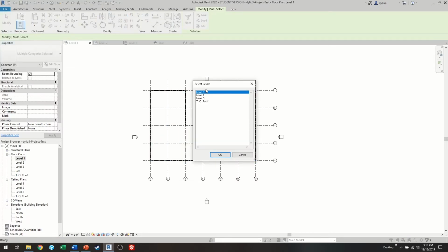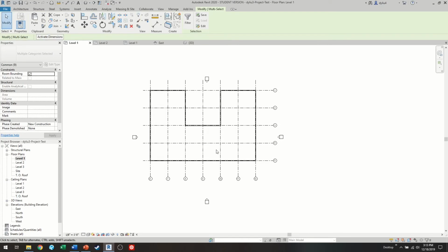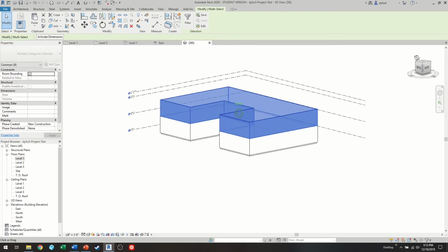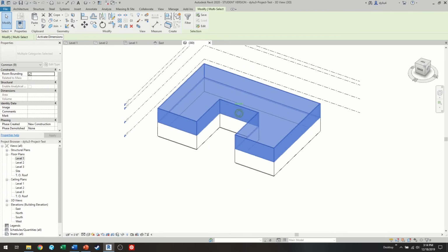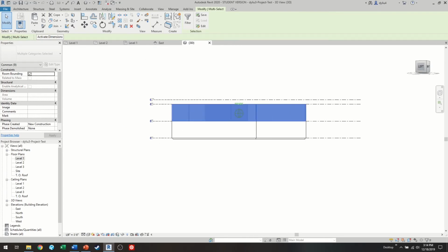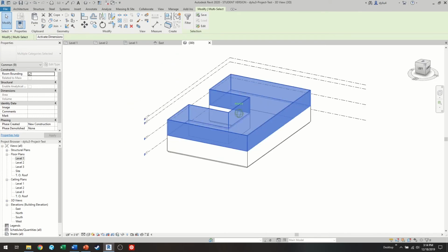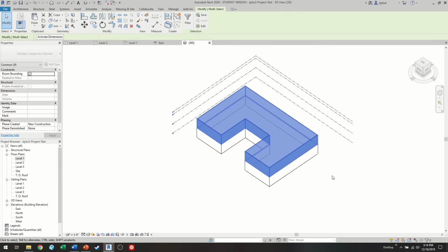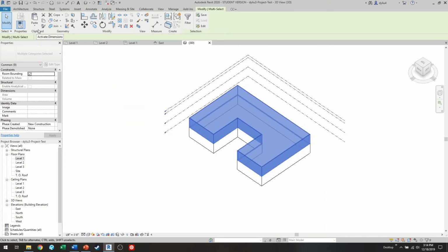I'm just going to paste everything I have also onto level 2. So now in 3D, rather than just one box, I have a box that has a floor. You see that? I've made walls and floors for 2 different levels, so I don't have to remodel everything if it's basically got the same outline, and I can only take the things that I need for this floor. Take a moment to catch up if you need to, rewind if you have to. I'm going to keep going by making a roof.